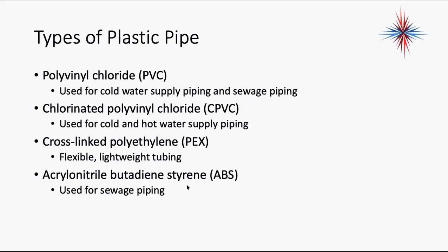It sags. Honestly, if I had to repipe my house, I'm going with PEX because I can pull it through the walls just like wiring. It comes in 150-foot rolls, and I don't have to make any joints between the fixture and the main water supply. PEX tubing is being used very often.